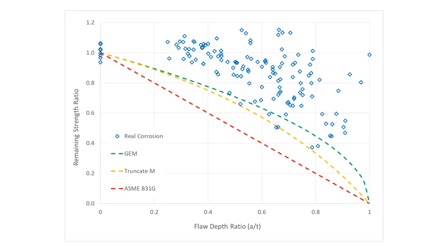And you'll see that this relationship is not perfect. We have, I think, 5 or 6 of our data points that are below the GEM limit. But given that there are so many data points, I'm going to consider that there's a bit of plus or minus error. And I still feel that my GEM model is worth considering, even though there are a couple of outliers here. So now I have to ask myself the question, if the Kiefner TTO5 fatigue crack length limit matches up very well with the natural length limit in the corrosion flaws, how does my GEM model come into play here? Is there any way that I can use my GEM model to come up with an equivalent fatigue length limit?